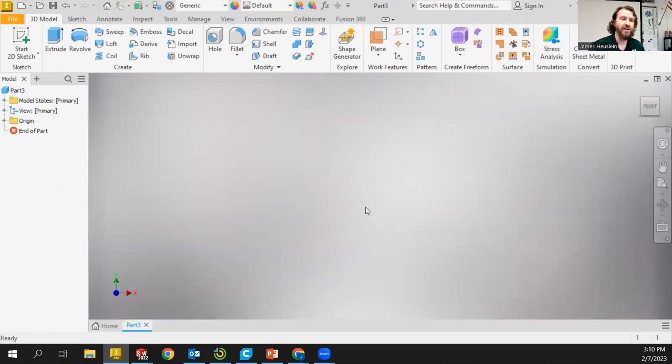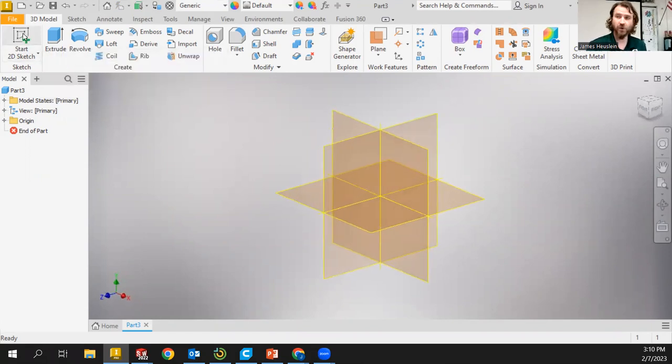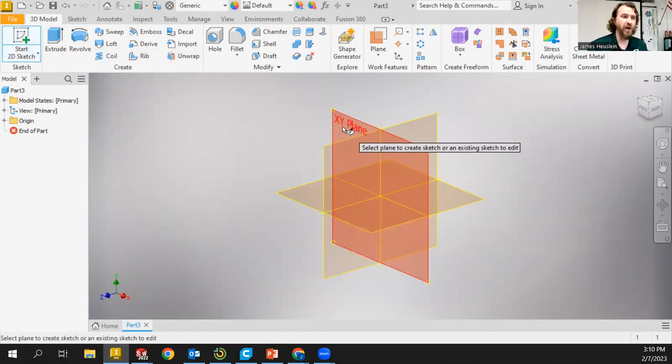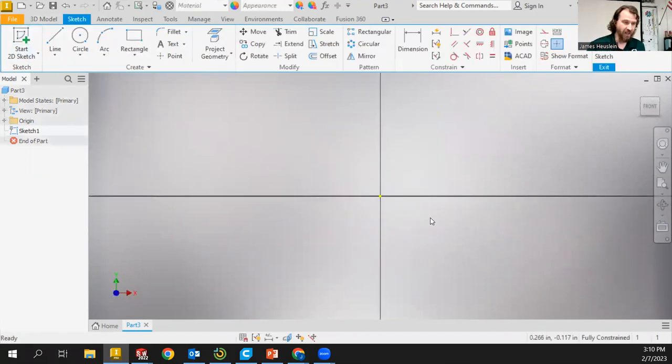And we're looking good. Now, if we reference the drawing, we were using the front view of this part to create this. So we're going to go to Start 2D Sketch, always where we start. And we're going to go to the XY plane. The XY plane has the X-axis and Y-axis in it, and our 0, 0 mark here, this is our origin, where X is 0, Y is 0. We like to start drawings at this point to give Inventor a reference of where you are locating your object inside the three-dimensional space. It's a reference point.